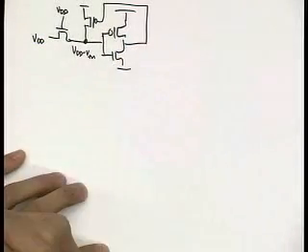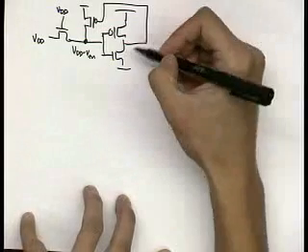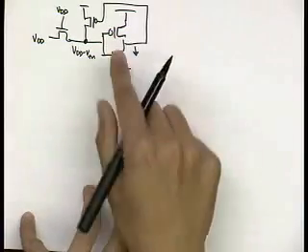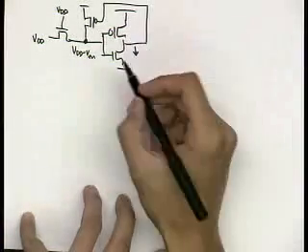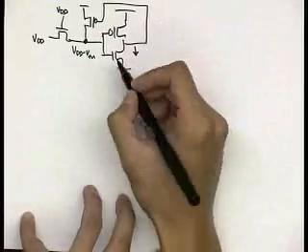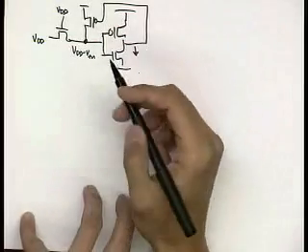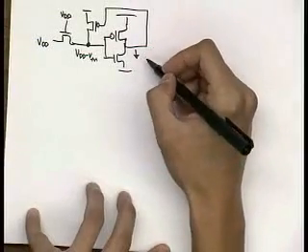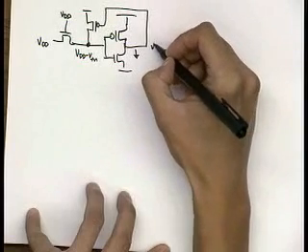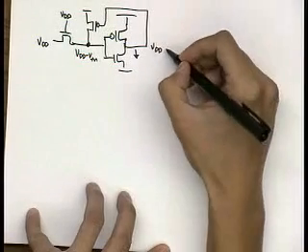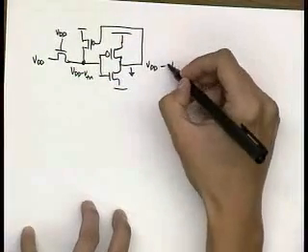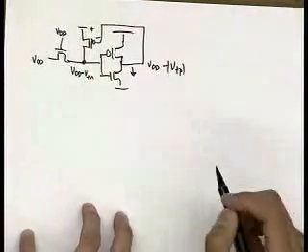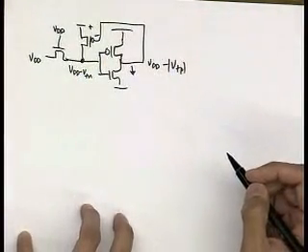And what happens? This should start to go down, because obviously VDD minus VTN would probably be greater than the threshold voltage of my NMOS transistor. So I'll pull this down, and what happens? I get to some value here, VDD minus VTP. So I actually get a threshold voltage across my PMOS.